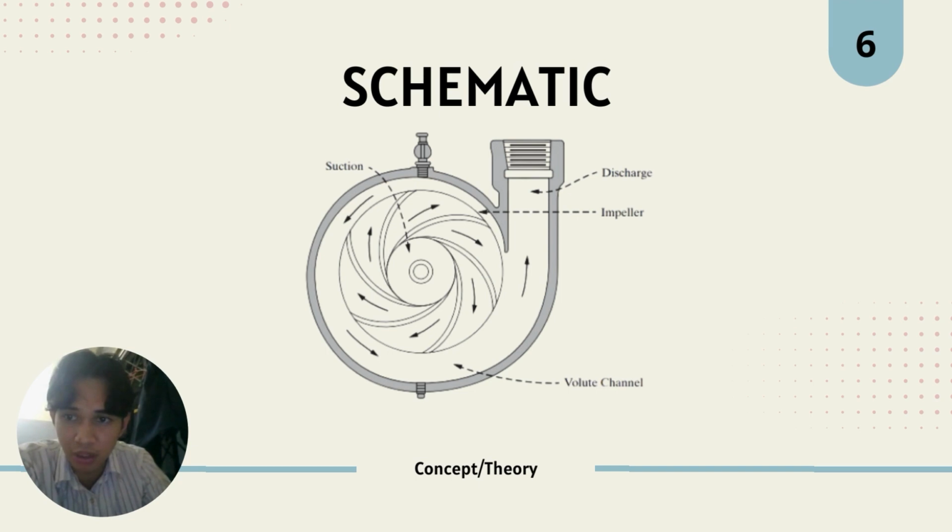This liquid is forced outward along the blades to the blade tips at an increasing velocity. At this point, the liquid has acquired an increased velocity head from the power input of the pump. The velocity head is then reduced and converted to a pressure head as the liquid passes into the chamber within the casing beyond the blades, and the pump is then discharged.